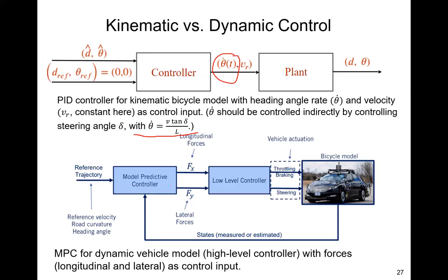This example is a dynamic model with MPC, with a high-level controller, MPC, producing forces, which are applied to the vehicle. These two examples just happen to be PID kinematic control and MPC dynamic control, but you can also have PID dynamic control and MPC kinematic control. You can do combinations.